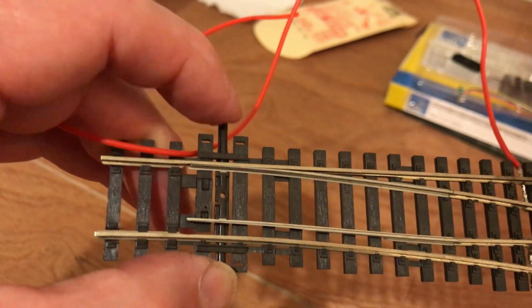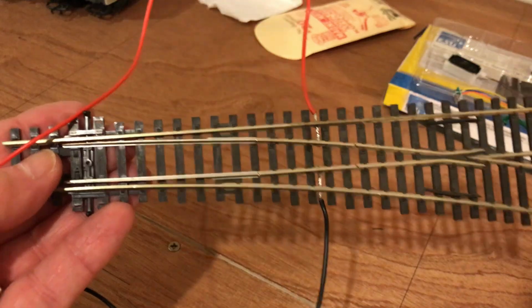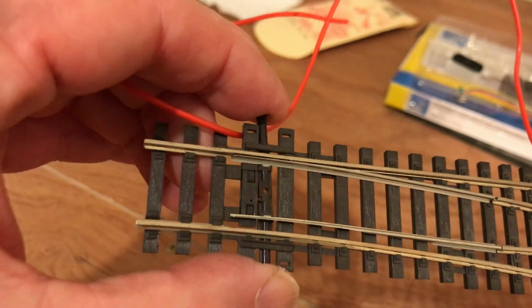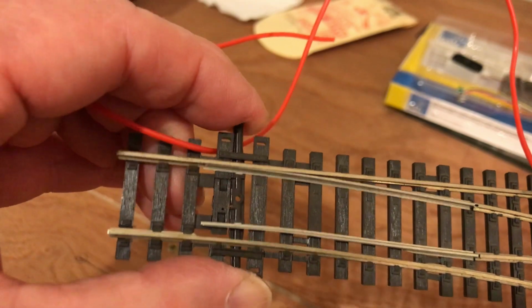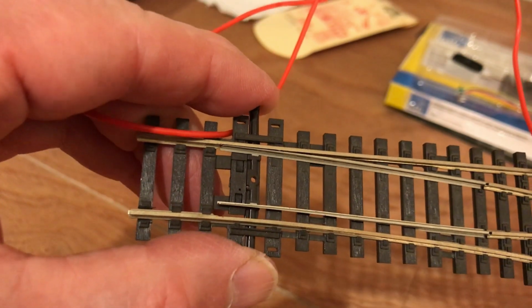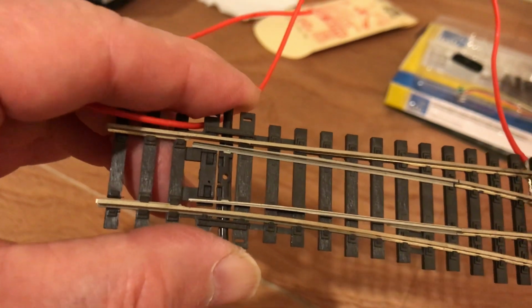Without the pressure of the spring, the blades can slip forward away from the frog, and the tip of the blade fails to close properly because it's no longer sitting in the notch in the stock rail. It's thus important when fitting slow motion point machines to have the actuator spring wire with a positive bend towards the frog position to recreate the effect of the original spring.